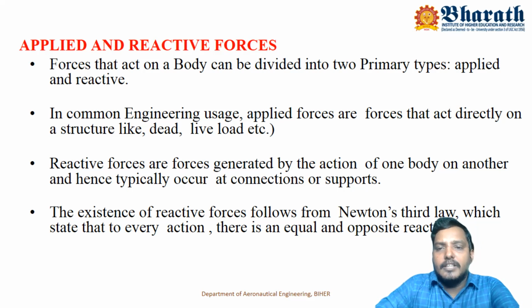If we consider a building structure, inside the building people are moving around. Therefore, the load keeps on varying with respect to time, and then it is called a live load. Then the reactive forces are forces generated by the action of one body on another, and they typically occur at connections or supports. The existence of reactive forces follows from Newton's third law, which states that for every action there is an equal and opposite reaction.